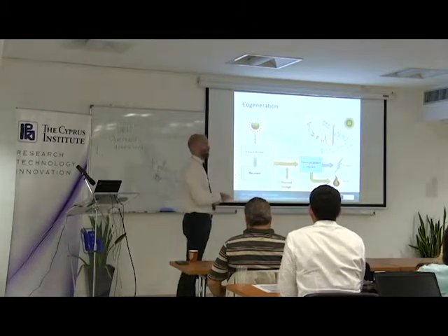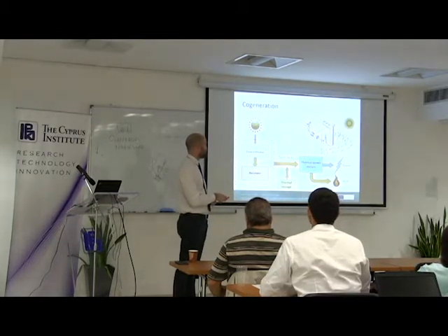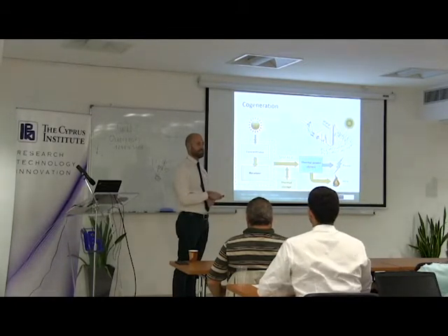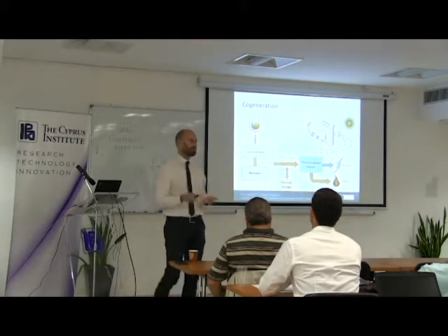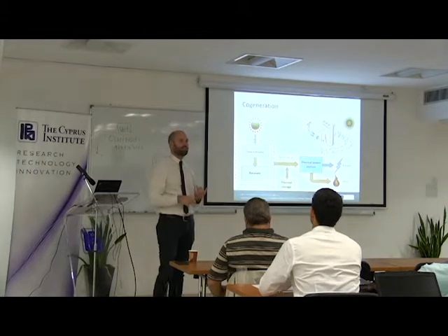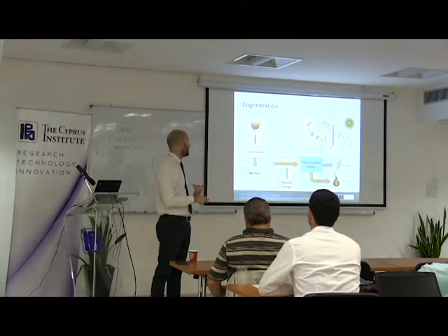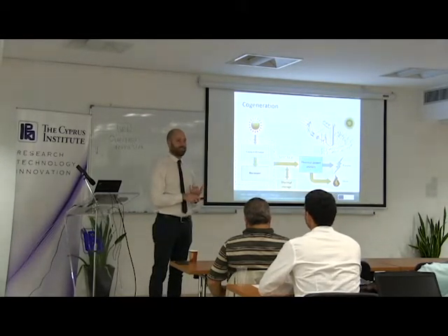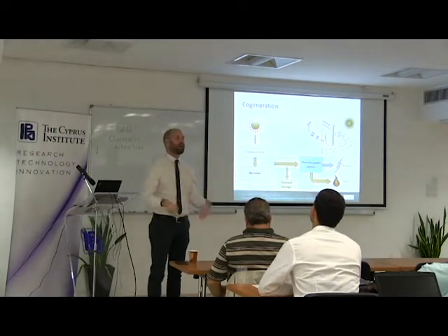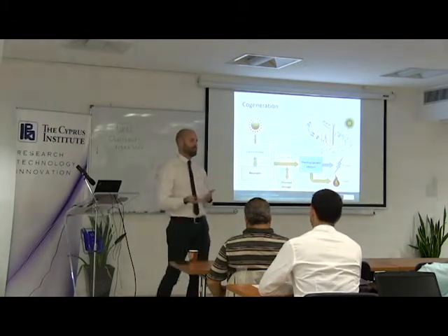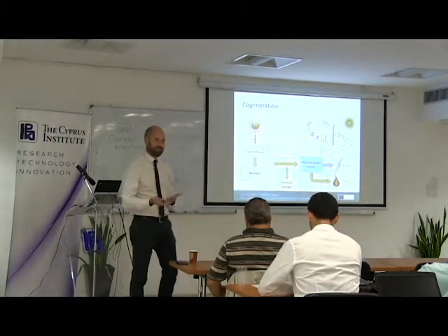However, when you follow this approach, which means that you use rejected heat from the thermal power station, you have two competing requirements. Because from the point of view of the power station, you want to keep the temperature level of this heat as low as possible, because this means higher thermal to electricity conversion efficiencies.